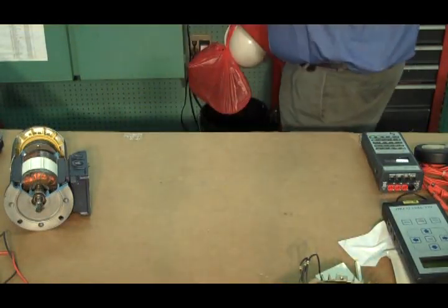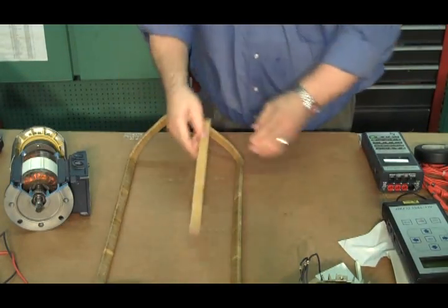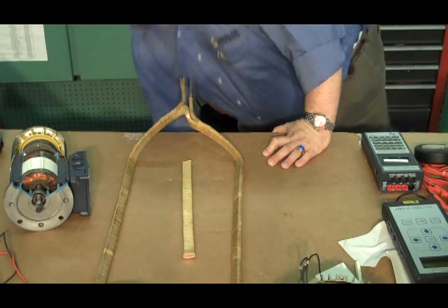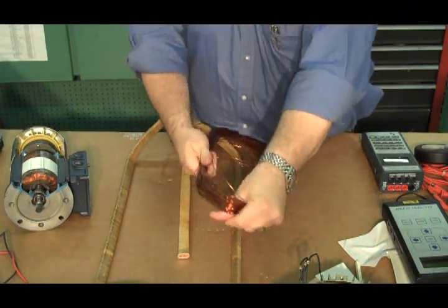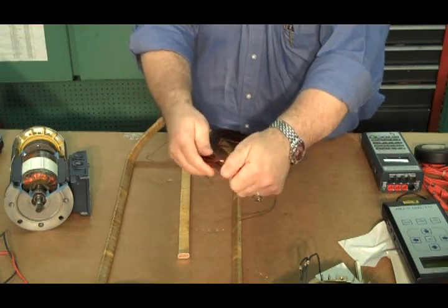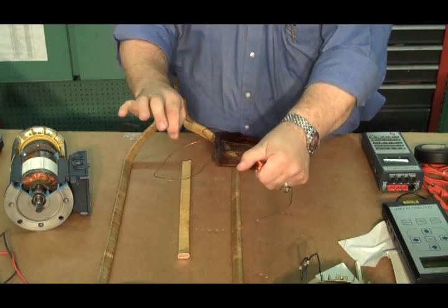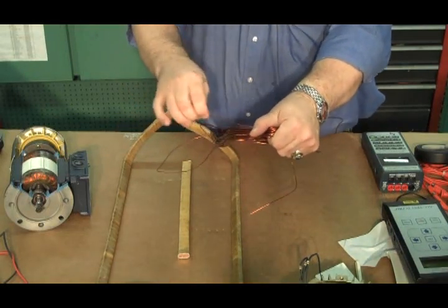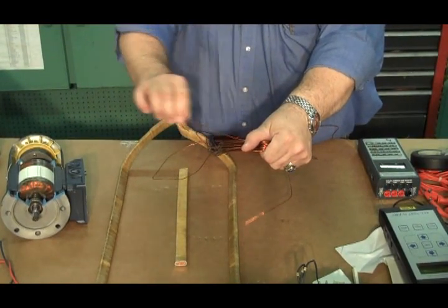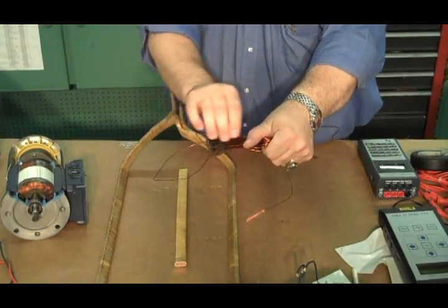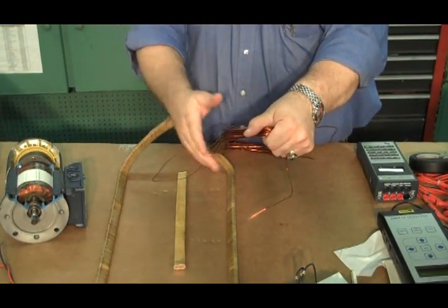Now, the insulation system, or the coils, are made up of different materials as well. On my low voltage machines, or your under 600 volt machines, this material is your wire. The wire will be usually copper, sometimes aluminum, and it'll have an enamel coating on it. The enamel coating is your actual insulation system for the electric motor. It acts like a pipe, and then the copper wire acts like the center of the pipe where your electricity or your water would flow.